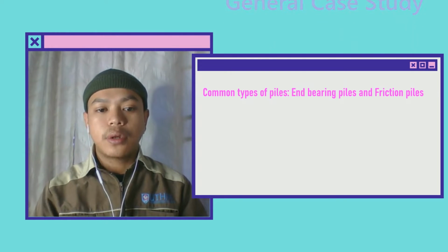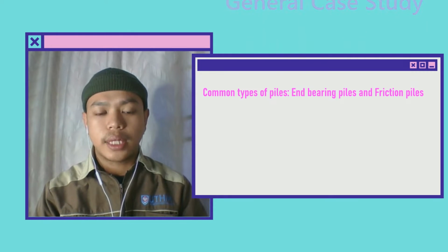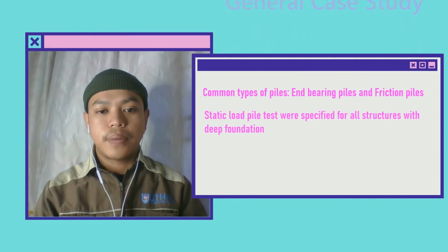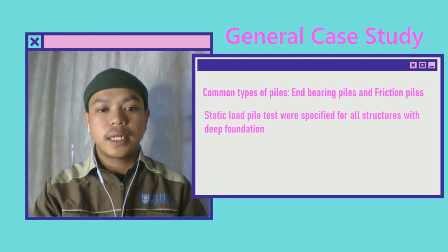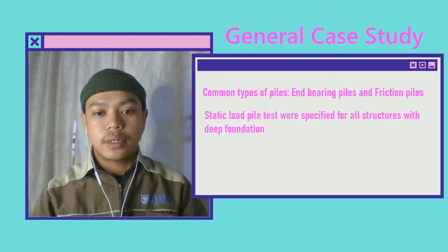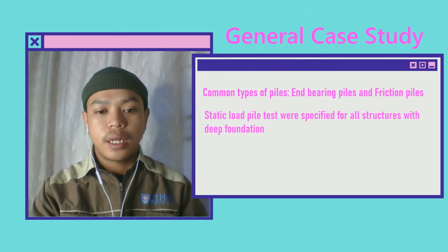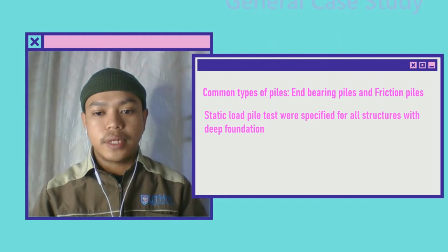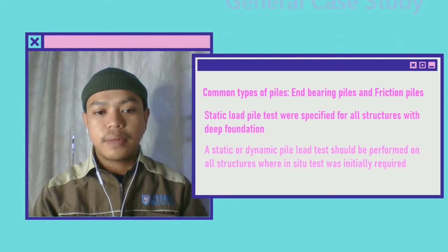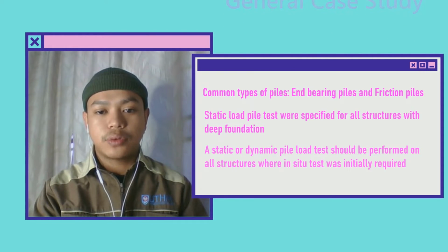It can be done on a driven pile or cast, on a working pile or test pile, on a single pile or a group of piles. Static pile load tests were specified in the tender plans for all structures with deep foundations, in accordance with conventional design practice for the finalization of the foundation design. The most significant aspect of the proposed pile load test program was that a static or dynamic pile load test should be performed on all structures where an in-situ test was initially required.